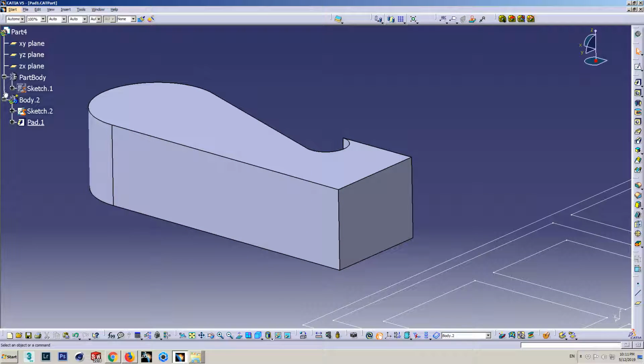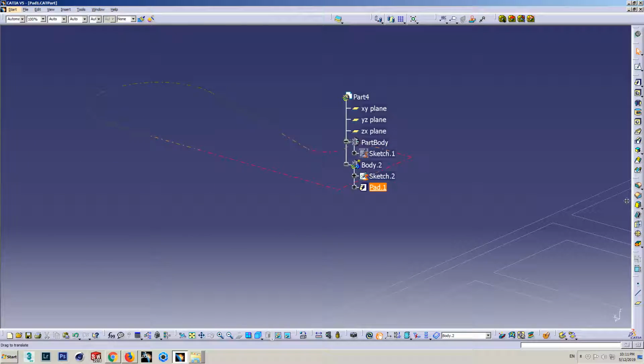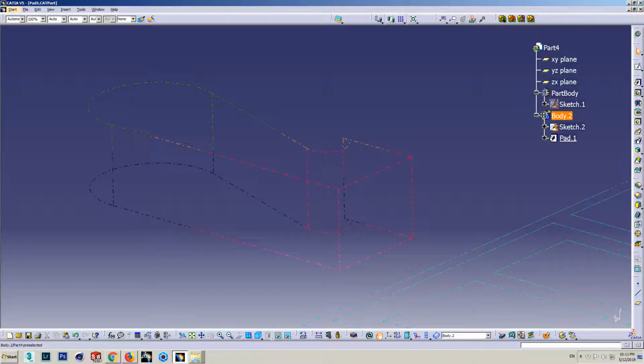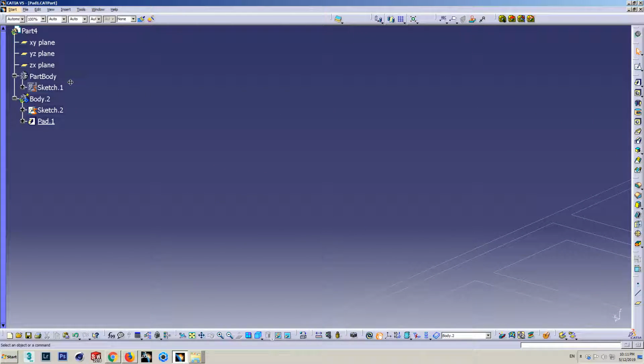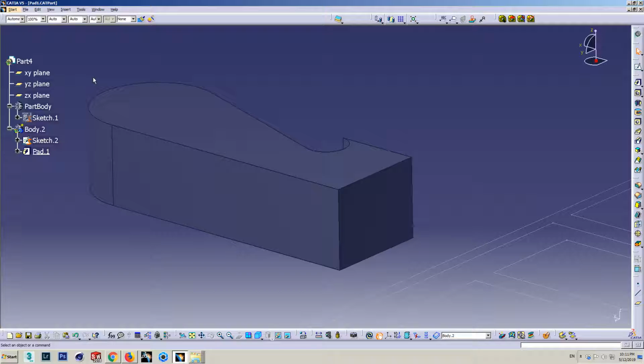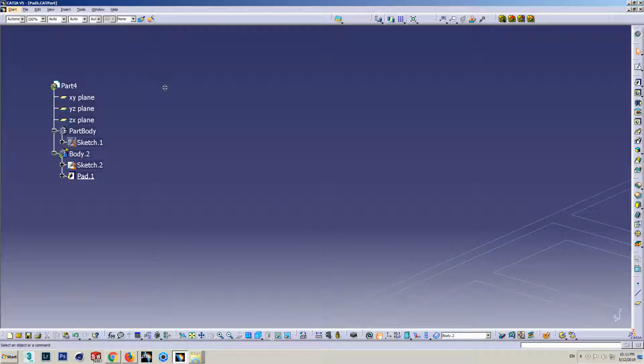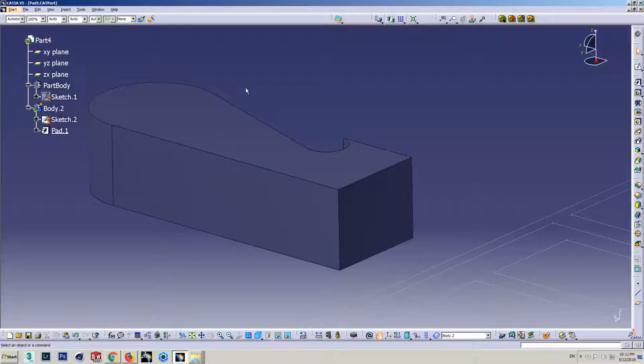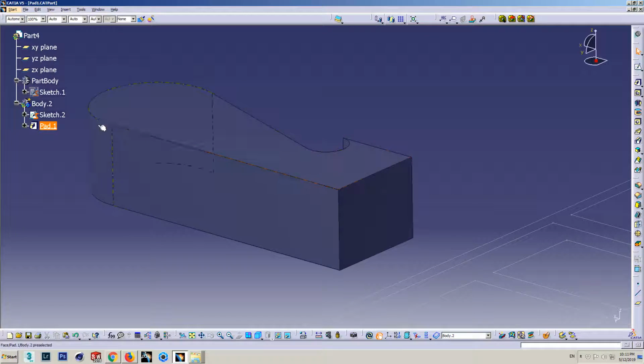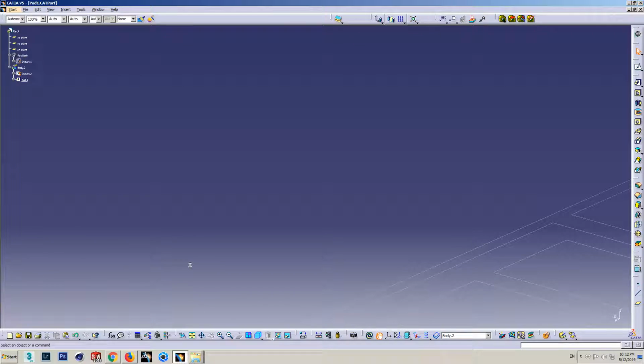You go with the mouse cursor on top of any of these link branches, click it, and then you can drag this in another direction. But usually it's over here on the left. You can also scale it. While you are dragging this with the middle mouse, your part will be gray and frozen. Now if I try to zoom in, I will zoom in and zoom out within this branch.